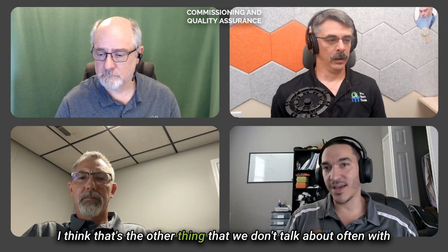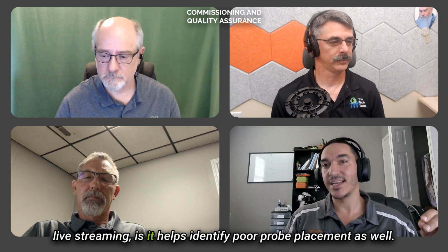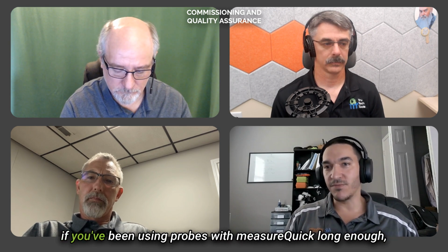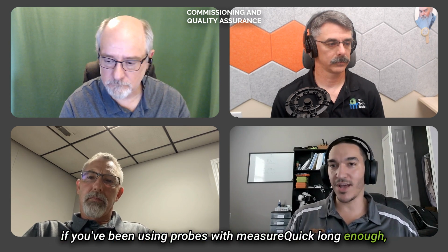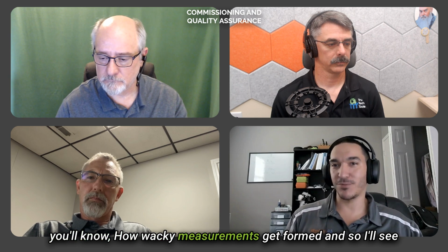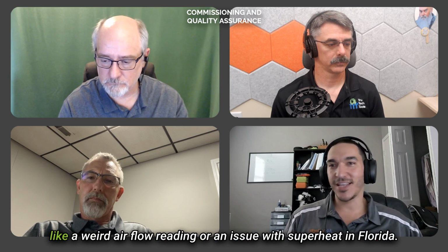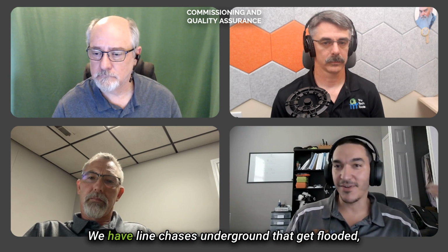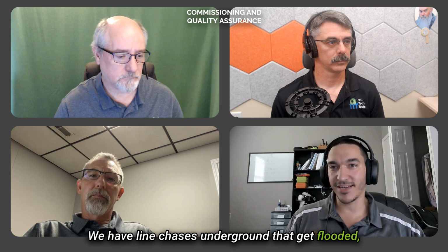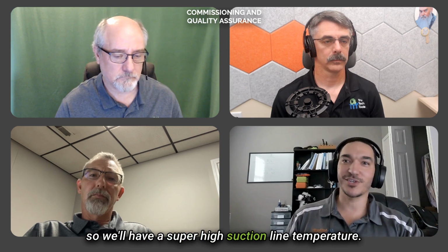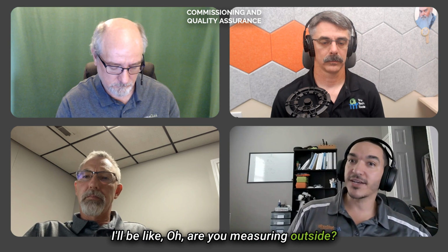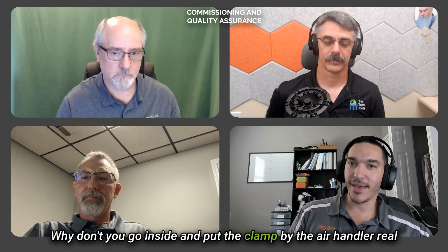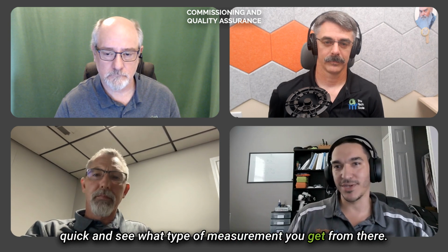I think that's the other thing that we don't talk about often with live streaming, is it helps identify poor probe placement as well. If you've been using probes with measureQuick long enough, you'll know how wacky measurements get. And so I'll see a weird airflow reading or an issue with superheat. In Florida, we have line chases underground that get flooded. So we'll have a super high suction line temperature. I'll be like, oh, are you measuring outside? Is the line set running underneath the house? Why don't you go inside and put the clamp by the air handler real quick and see what type of measurement you get from there.